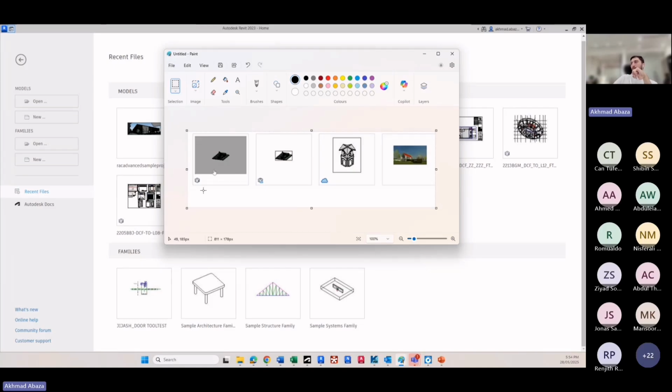Once we create our local file, we will work on this local file and synchronize with central every period that will be agreed between all the teams. For example, everyone working on this file has to synchronize at end of business, close of business. So this will be agreed in the team itself.